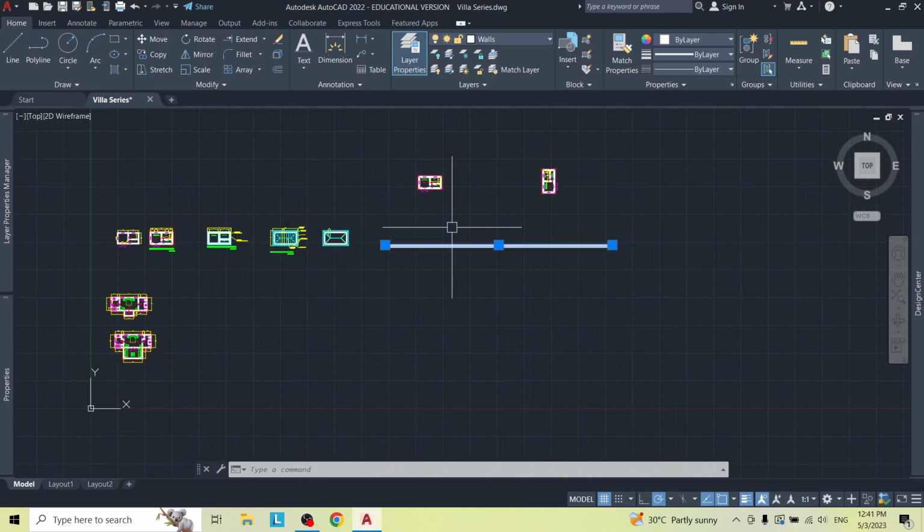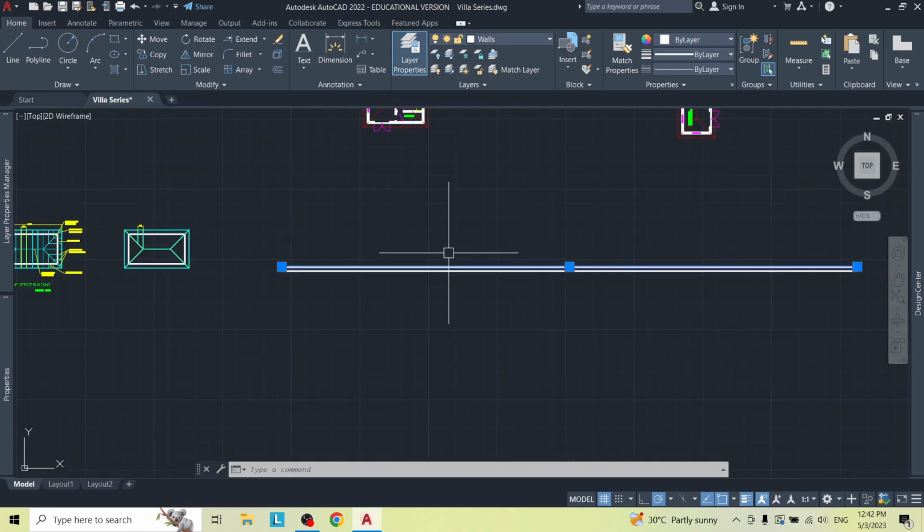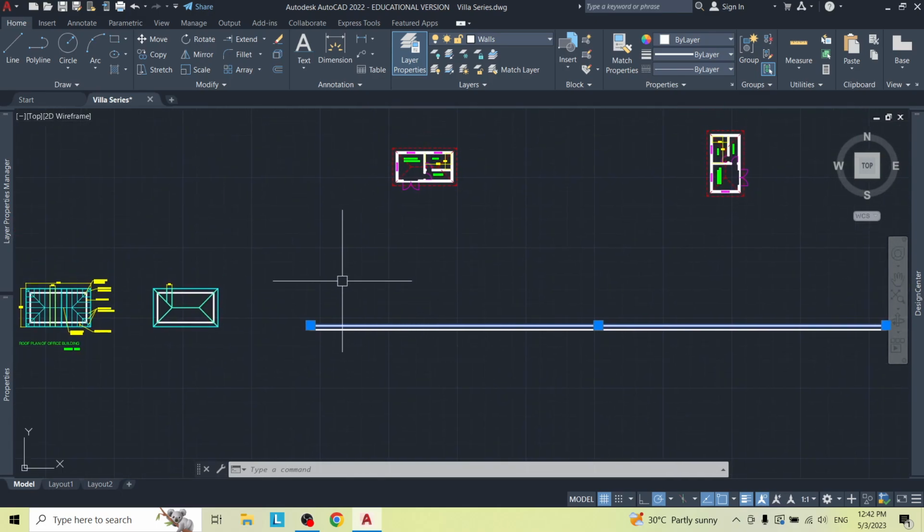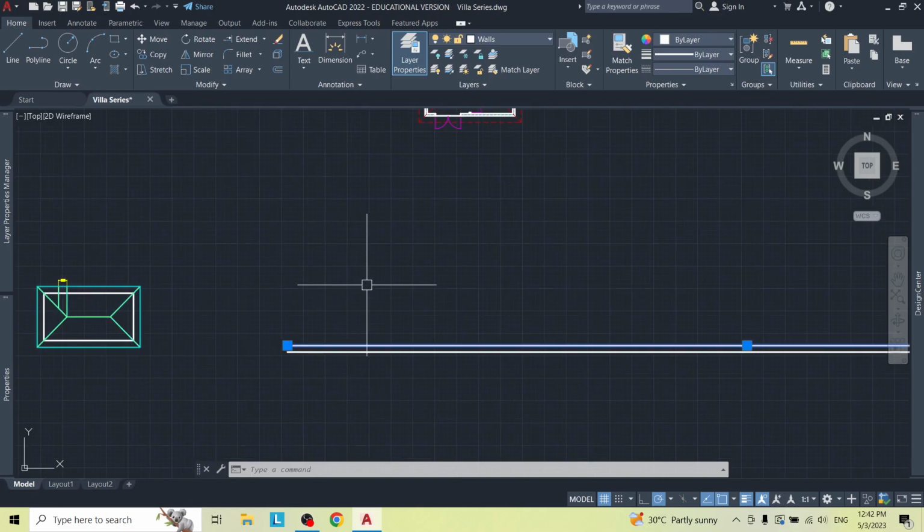Let's forget about the top of the wall technically for now, and put in the measurement for where your fascia board is going to go. This is what we call the eave line. We'll come back and fill in the other details after. So the eave or the overhang, that's the line I want us to draw now. So let's put that 9 feet above the floor of our house, not the ground line.